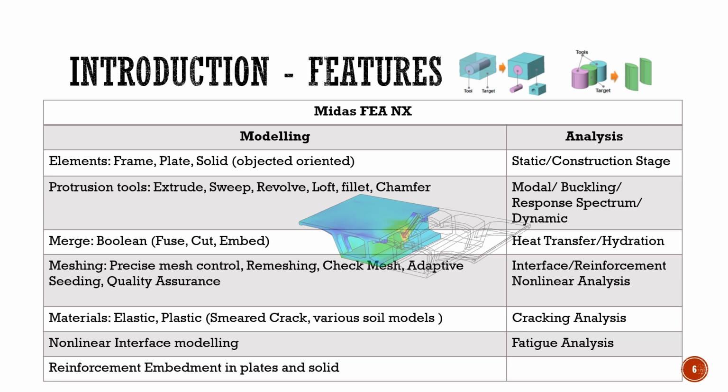Further, it offers Boolean operators which can fuse, cut, embed, intersect the two solids or surfaces, which is quite useful for creating complex geometries for the FEM modeling. In material properties, MIDAS FEA NX supports additional nonlinear properties over and above MIDAS Civil, such as smeared crack model, several other nonlinear soil models for generating the FEM models.